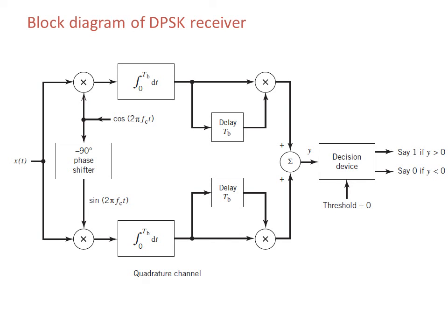This implementation is simple in that it merely requires that sample values be stored. The receiver here is said to be optimum for two reasons. In structural terms, the receiver avoids the use of fancy delay lines that could be needed otherwise. In operational terms, the receiver makes the decoding analysis straightforward to handle, since the two signals to be considered are orthogonal over the interval 0 to 2TB.